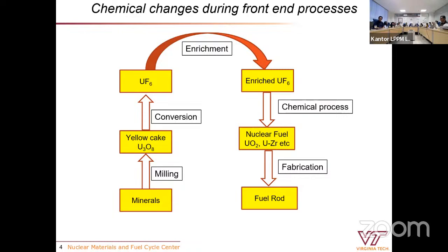So the other question you said, LOCA, right? Loss of coolant accident. For this molten salt reactor, we do not have that issue. For the water-cooled reactor, you get your water out, it's completely released somewhere. But your fuel is still in your reactor. It continues to produce heat. If you do not remove that heat, it will heat the cladding to a high temperature, then it melts.